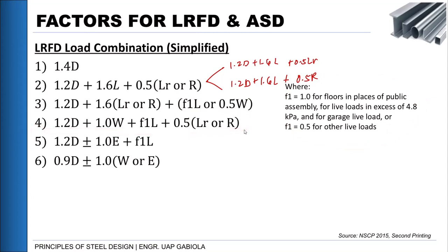And then as you can see, for wind and earthquake, why do you think the value is only 1.0? The answer is that when we calculate the wind load and earthquake load acting on our structure, there is already a set of equations and factors used, and those factors are all based on the LRFD approach. So when we multiply a value more than 1 in the load combo, it becomes a repetition, or over, overlapping the magnification we already apply. That is why it is only 1.0.